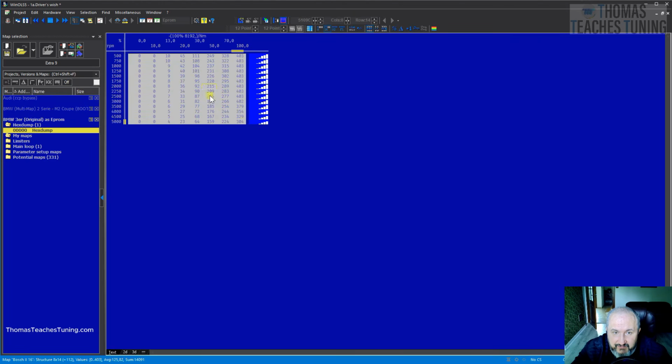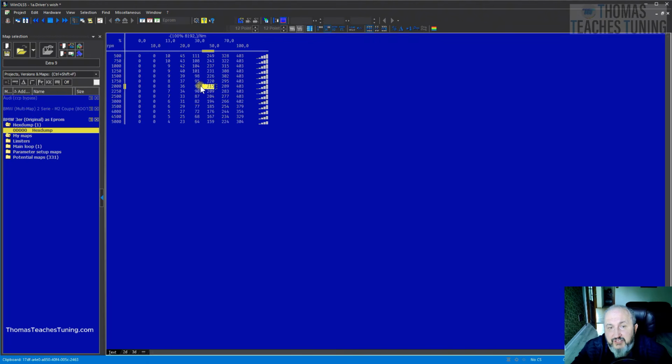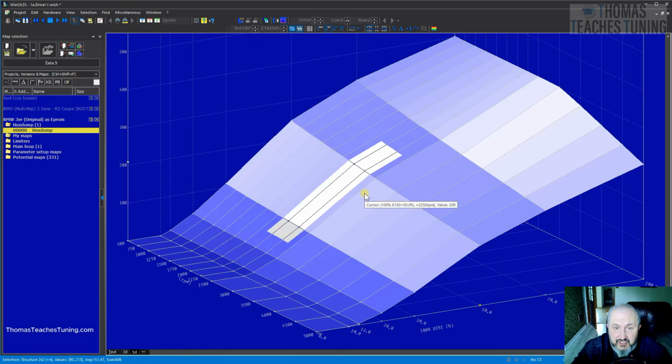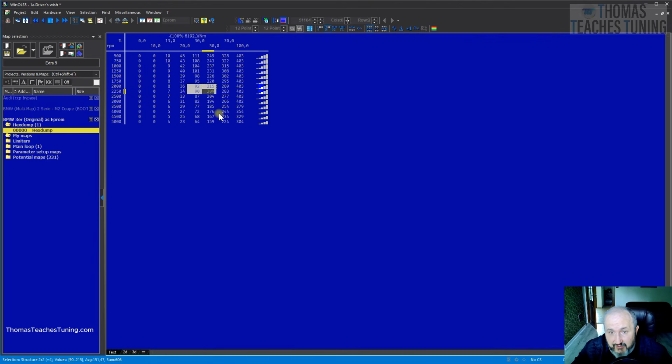The values in the system are interpolated. If there is an instance where the value is not exactly defined, such as exactly 1850 revolutions or so, the interpolation will be based on 4 points within the characteristic map. It is essential to remember that the values are always interpolated within this map, and nothing occurs in discrete steps. No steps, not at all.